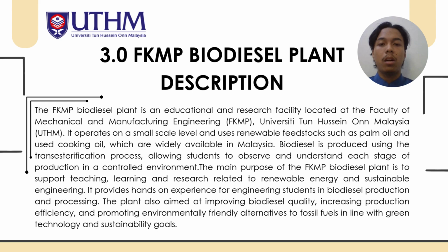It operates on a small scale and uses renewable feedstock such as palm oil and used cooking oil, which are widely available in Malaysia. Biodiesel is produced using the transesterification process, allowing students to observe and understand each stage of production in a controlled environment.